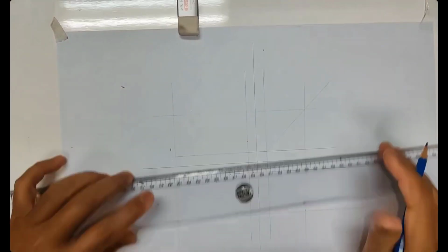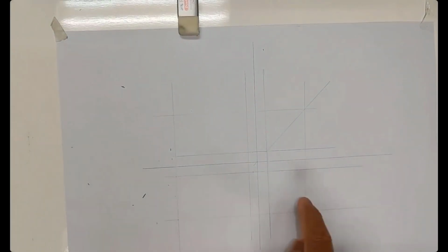Okay, you see the 45 degree line, so you have all the bounding boxes for front, side, right view, and top view. Okay, you already have the bounding box. Now, if you have this kind of question, if you look at this block, it has a cutting, like a chamfer. The main profile is cutting at a 45 degree angle incline. That is a straight plane, totally a straight flat plane cutting at 45 degree. So that's why in ISO view, we look at the view like that, at 45 degree.